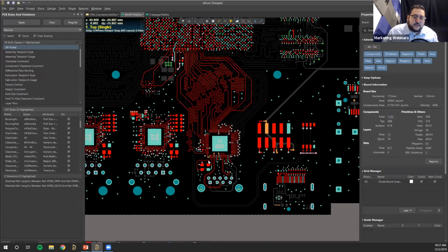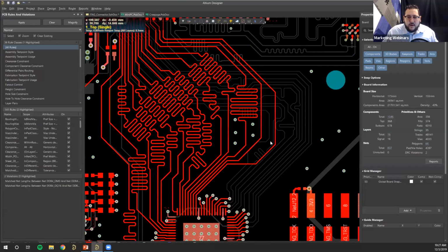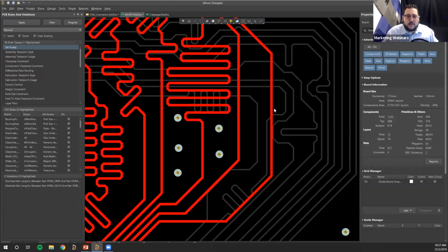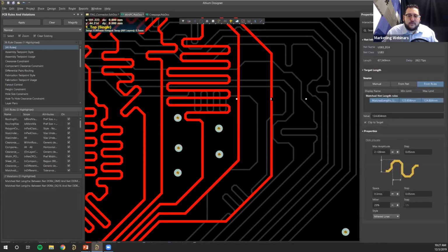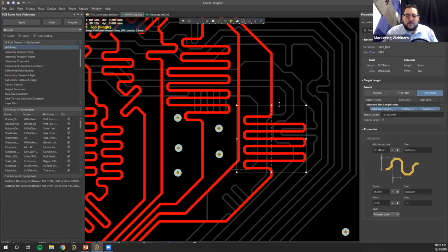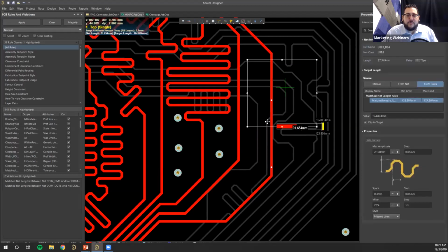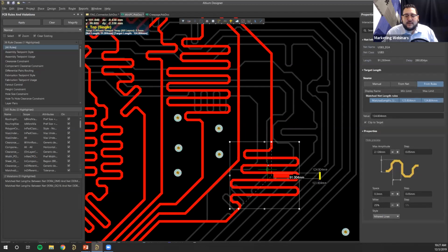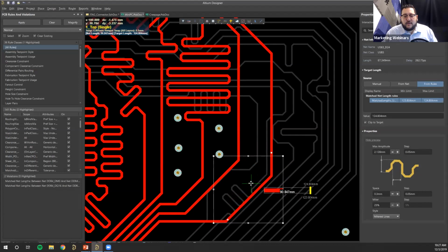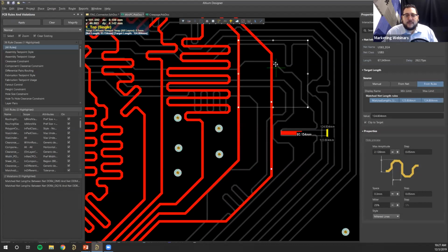Let's switch back to the front. We talked about area tuning. So I'm going to use the shortcut U and then R, right, to initiate area tuning to create a persistent shape. And I can just move the shape as necessary. You see, we can move it along this corner path here as necessary.